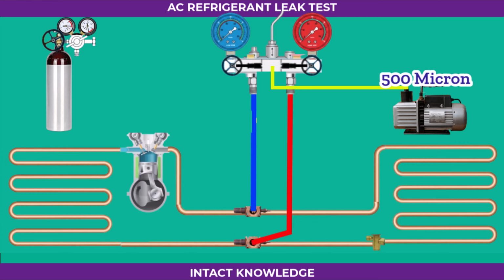If the pressure drops rapidly, inspect all hose fittings and valves again. A slow pressure drop could be from temperature changes, very small leaks, or residual air. And if the vacuum doesn't reach your target micron reading, you might still have a tiny leak, moisture, or restriction. In that case, repressurize with nitrogen and test again before doing another evacuation.